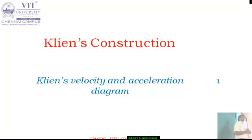In the last class, last semester, you studied the velocity and acceleration diagram by drawing the velocity polygon and acceleration polygon from the space diagram. But here, from Klein's construction, by using the space diagram itself, we can find out velocity and also acceleration. No need to draw the velocity and acceleration polygon separately. That is the main advantage of Klein's construction.